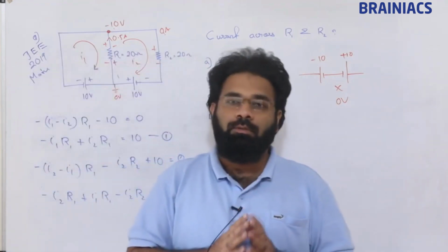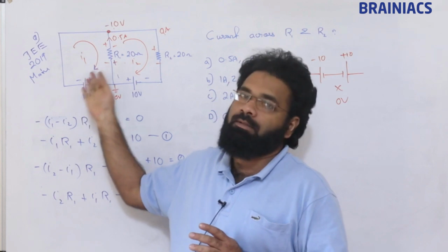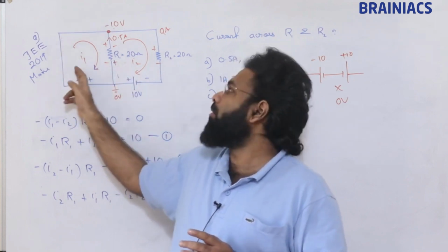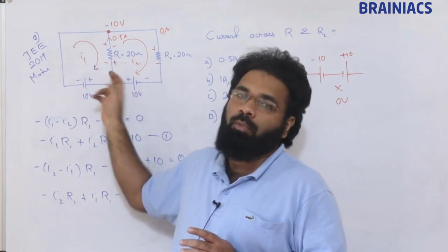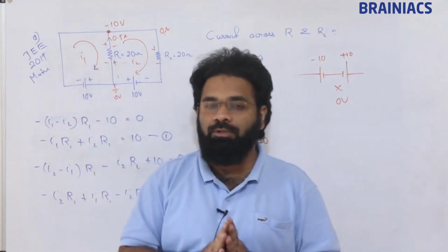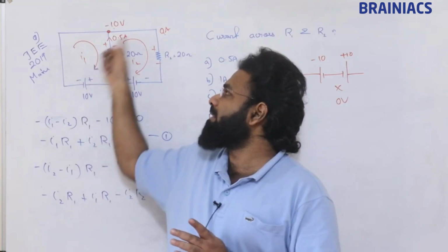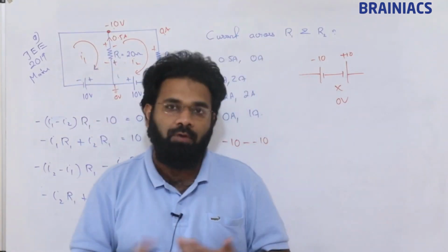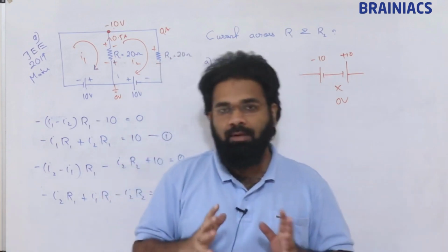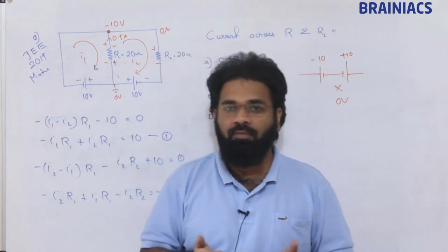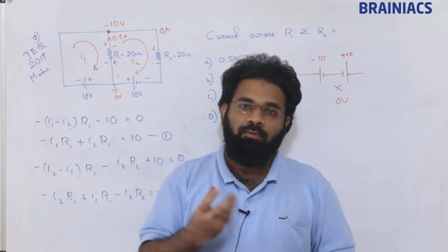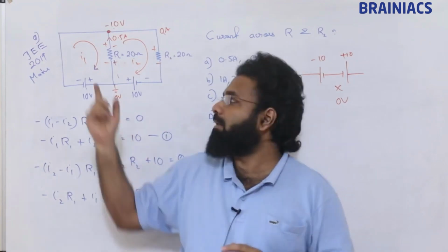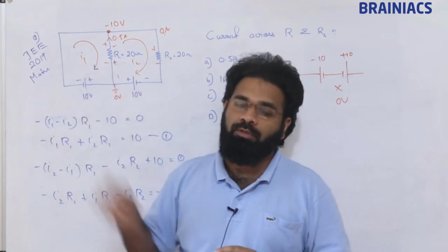So students, if we use nodal analysis, it is easy. Even if we put a resistance here, we can solve this problem with one equation. If we use mesh analysis, that is KVL, we get two equations and two unknowns, and we have to solve all that. So be ready with nodal analysis. Difficult problems we can solve in a few seconds. Then the cubic cube network.